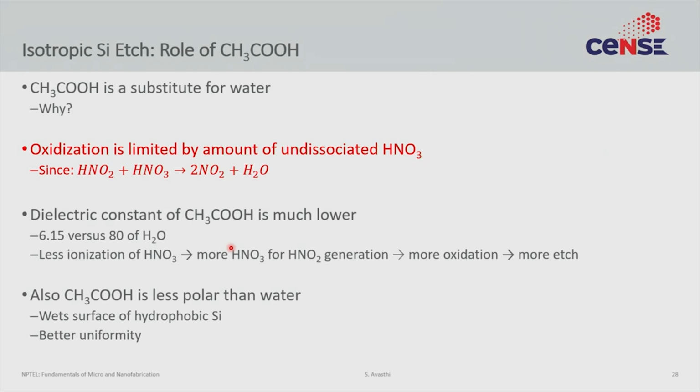Now when you are etching silicon, you are going into this pathway where you are forming silicon dioxide, but then you are etching the silicon dioxide which exposes fresh silicon, and that fresh exposed silicon is now hydrophobic. So if you can do this whole reaction in a medium that wets the hydrophobic surface better, then you would get better performance, better uniformity, better etching.